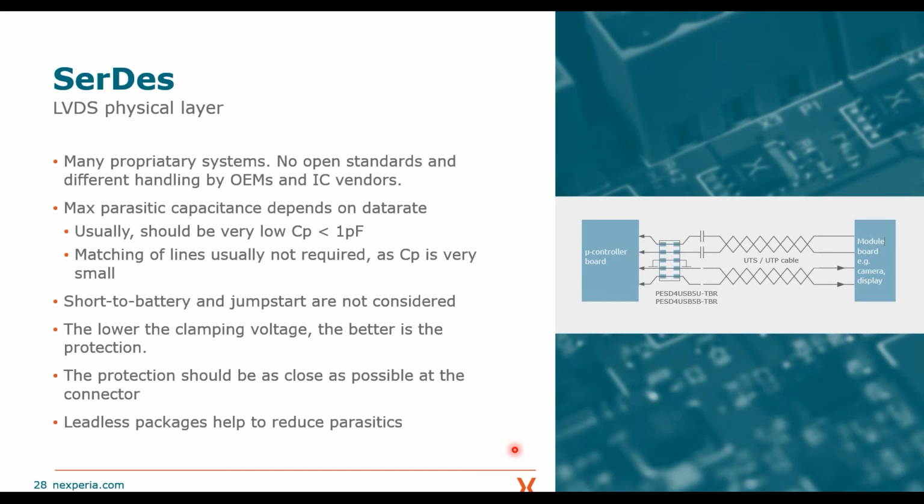for your PHY. Again, the ESD protection should be placed close to a connector, as close to a connector as possible, and when you recap all the slides we have shown you, we recommend this in all automotive applications, or for all ESD protection applications.